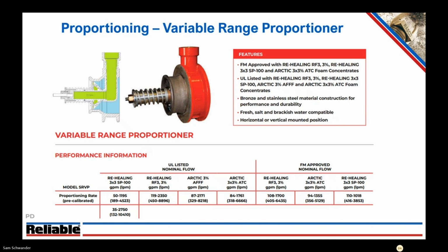As having something in the water path, as the flow rate increases, you're going to have higher levels of friction loss across a device like this than you would with just a ratio controller. So we're using this for something like flammable liquid storage in a warehouse, closed head sprinklers, or something where you might have one proportioner covering multiple zones with very different flow rates. So 2 different types of proportioners we want to be aware of.